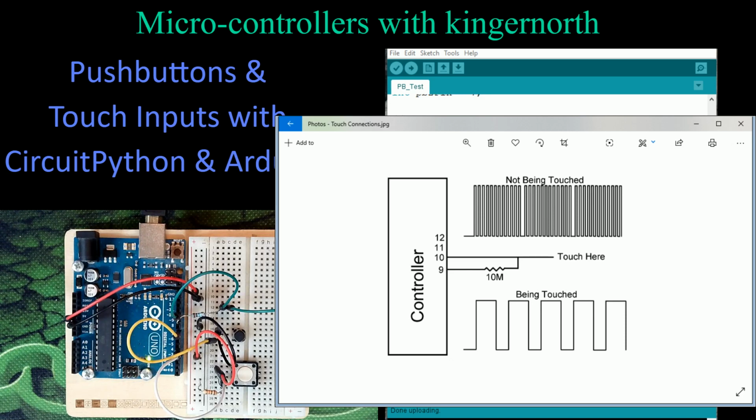Otherwise you get too much current and it takes way too much drain when somebody touches it to have it shut down. Your car might even be using 100 million ohms, because the higher the resistance is, the further away you can be from the wire when you touch it and complete the circuit. The advantage of your car is the body of your car is a large ground plane. It's connected to the common, to the negative terminal on the battery in your car.